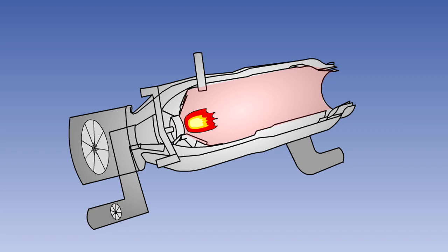Some aircraft use a combustion heater rather than an exhaust gas heater. The combustion heater is a standalone device. It normally uses the same fuel as the aircraft's engines. It burns about half a gallon an hour. This needs to be taken into account when calculating the fuel required for a particular flight.